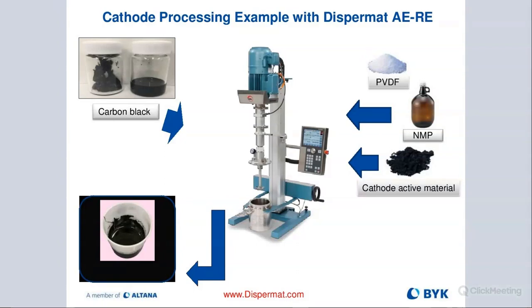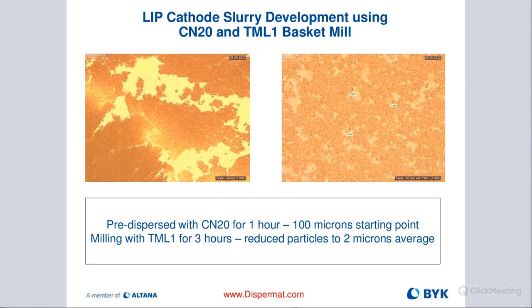We have the ability to also, if some customers like to do that in a more dry environment, add a port for inert gas, so we can use that in lieu of other materials. That's the option there. Argon gas or nitrogen. Some customers prefer to have a nitrogen blanket, so we can create that with that particular machine.